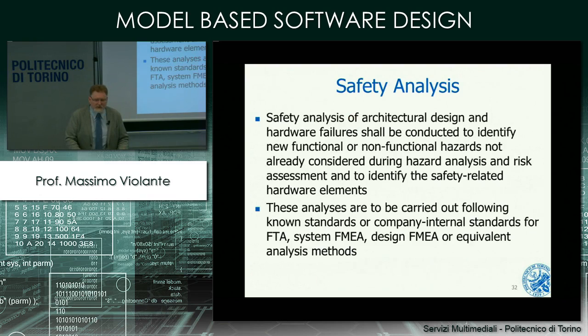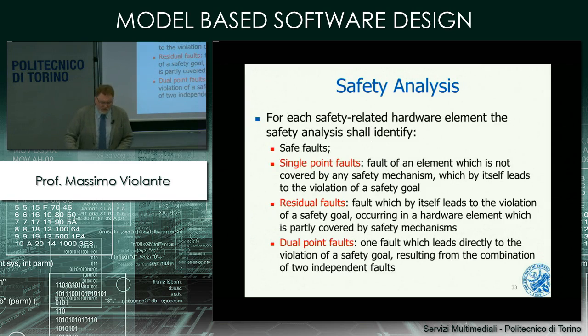Then, once your hardware design is done, you have to do an analysis. This analysis is based on certain metrics. Those metrics are the ones that could provide you a good indication of the residual risk associated with the usage of that hardware. And these are, for example, single point faults. That is the amount of faults that are detected by the mechanism that you placed in the hardware. The residual fault metric, that is the amount of faults that could impair the normal operation of the item that your mechanisms have not been able to detect.